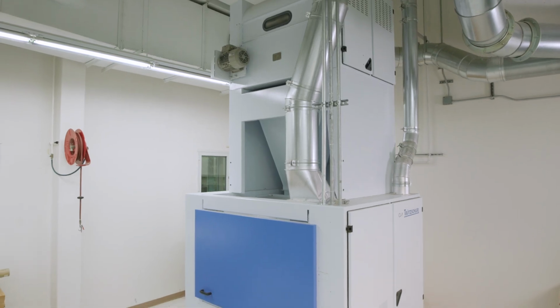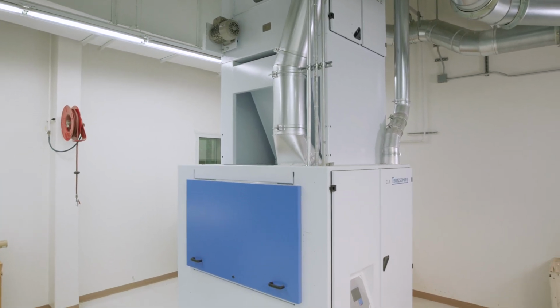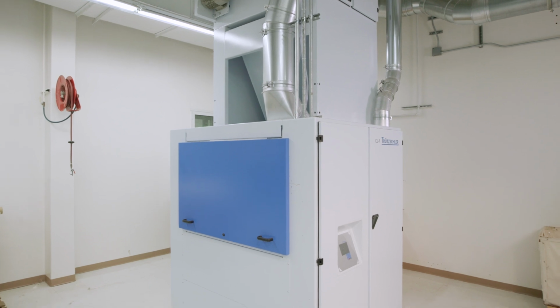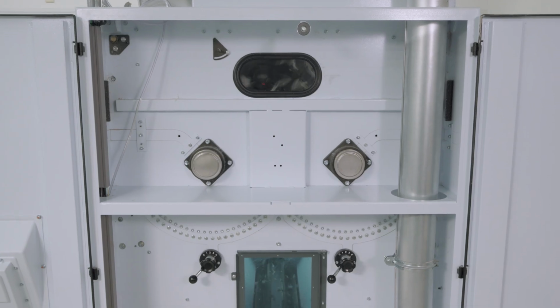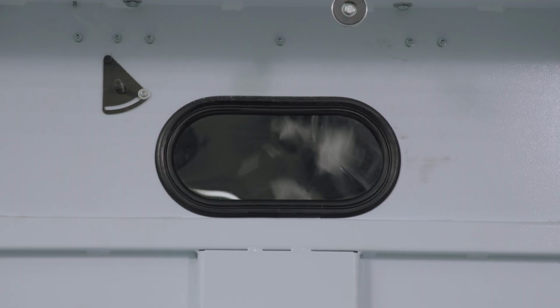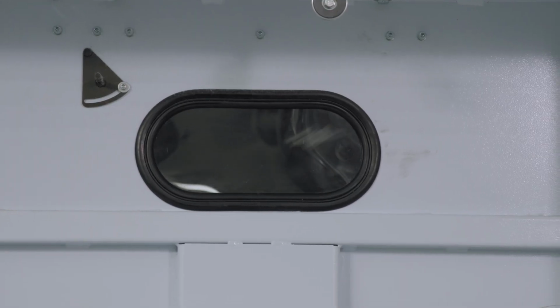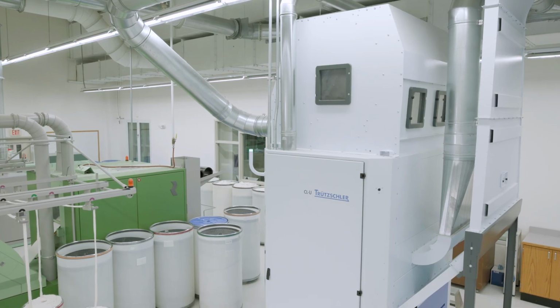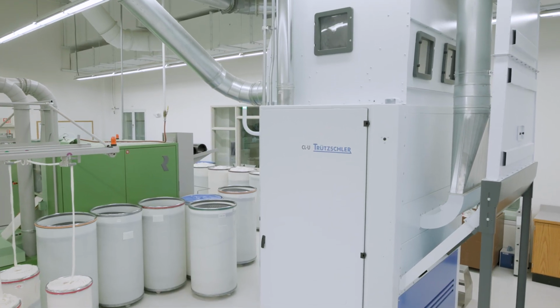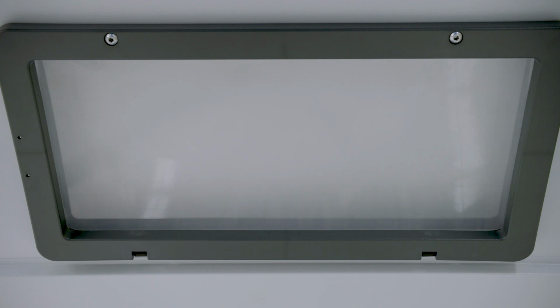From the opening and blending processes, the open fiber tufts are transported to the first of what may be multiple cleaning machines or steps. The first cleaning machines are usually designed to be coarse cleaners. That is, they're designed to remove the larger and heavier trash particles. Fine cleaners will be found last in the cleaning line and just before carding.